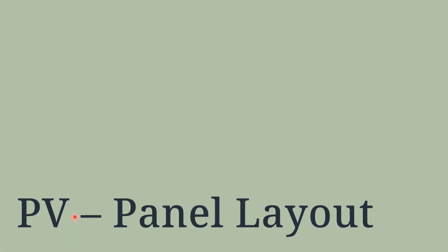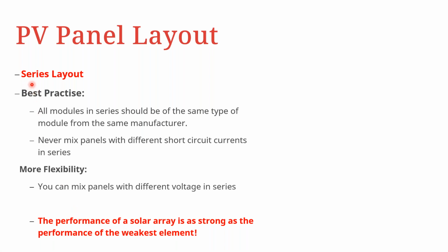So on the PV panel layout, you've got a series layout. This is a best practice where all modules in series should be the same type of module from the same manufacturer, as well as never mix panels with different short circuit currents in series. This allows for more flexibility, so you can mix panels with different voltages when they are strung in series. And the performance of the solar array is as strong as the performance of the weakest element, which is an important note.